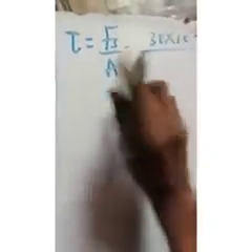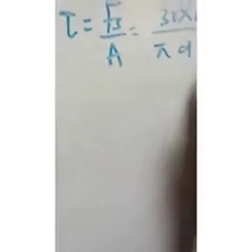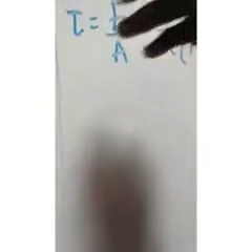You are given the force as 30 kilonewton, that is 30 times 10 raised to power 3 newton, all over your area. From the question, you make use of pi d square over 4. So that is pi, and your d is 10 millimeter. You can convert to meter, that will be 10 times 10 raised to power minus 3, over 4. You solve that and find your answer.